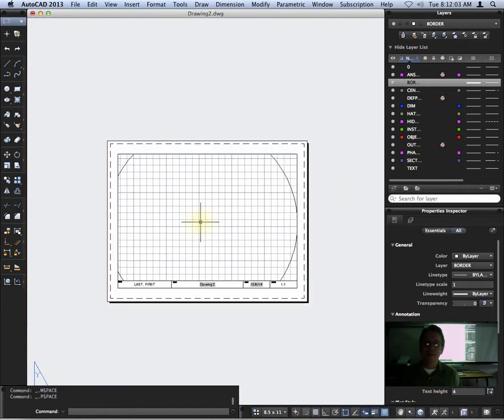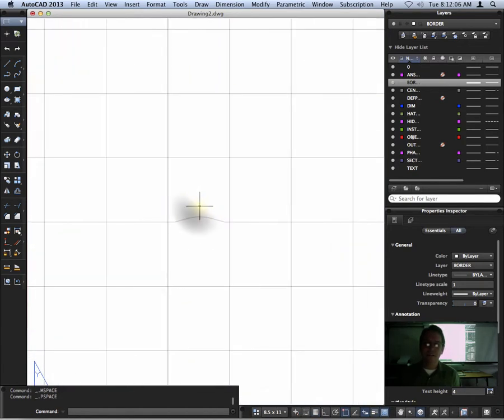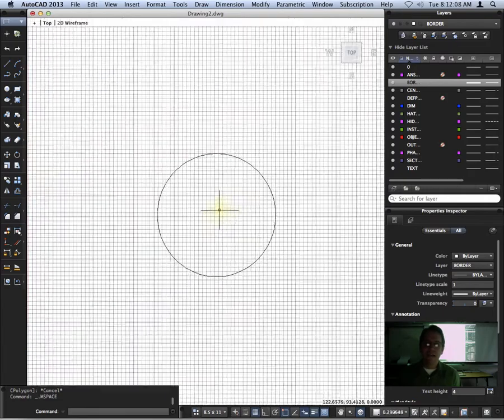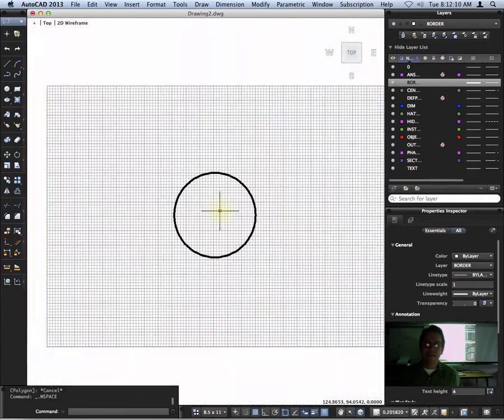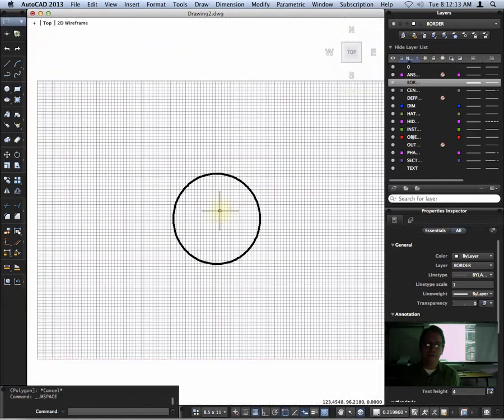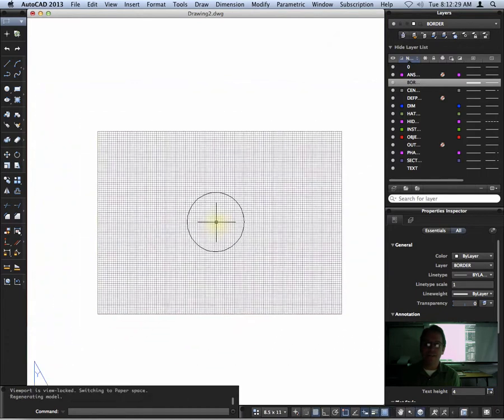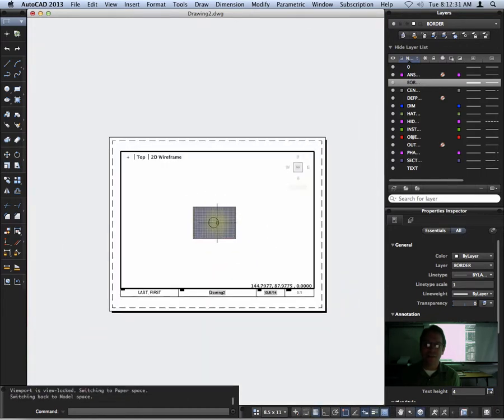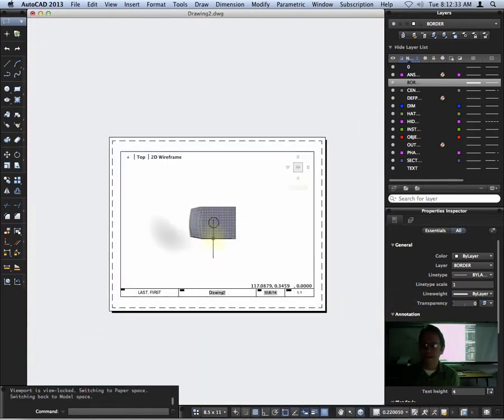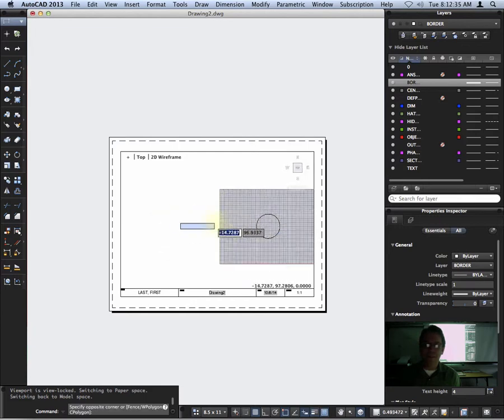So something that often happens is students zoom in really close. Now they double click, and now I'm zooming in and out of my viewport. But where's my piece of paper? I can't zoom out of my paper. There's probably some command for this, but I haven't been able to find one. The only way I've figured out to zoom out is to lock your viewport, to lock it down here. Now I've locked my scale. Now when I zoom out, it's actually going to zoom out my paper all the way. Then I can unlock it and zoom in a little bit.